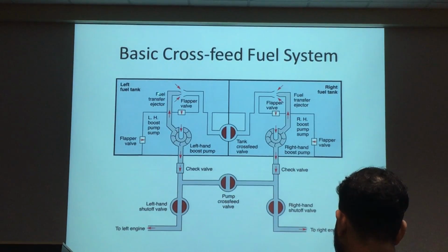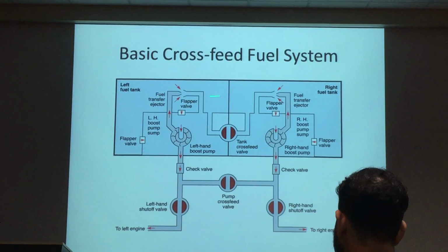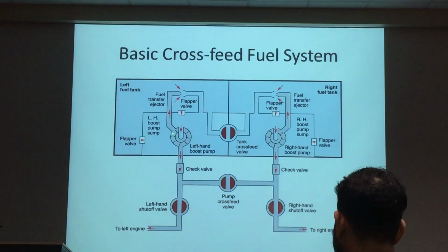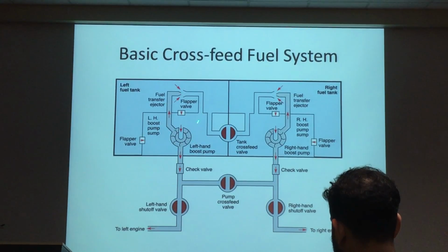So they introduce an injector pump. The diagram here shows the injector pump on top because of the display. No, sorry. The injector pump is here, lower level. You pump the fuel into this tank. So where do you get the motive force from? It comes from the boost pump. Remember the boost pump outlet is here, right? There will be a small tap from here. It will flow from here to the tank, circulating the tank.